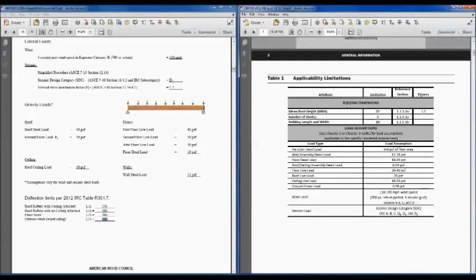So for the wood frame construction manual to even be used, here are the scoping provisions that say whether your building fits within those limitations. So you see that we've got a maximum 33-foot mean roof height, 3 stories, and 80-foot length and width of the building. For our loading assumptions, you can see those here for partition dead loads, wall assembly loads, floor and roof dead loads. Our floor live loads, this is where